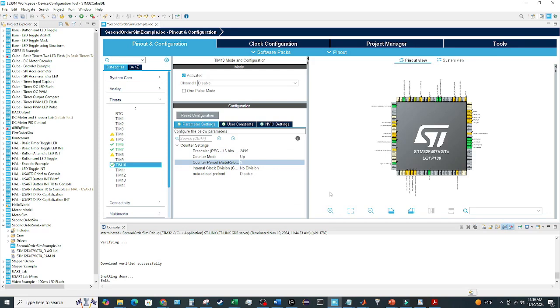Okay, so you can play with different prescalers, different period values. It's up to you how you want to decide, but the key is to pick prescaler values that give you reasonable periods that are within the limits of the timer. So the prescaler is limited here by 16 bits. This may be a 16-bit or a 32-bit timer, so the period in this case is limited to 16 bits. So you want to make sure that you pick values where both of these can be within 65,000 in this case.